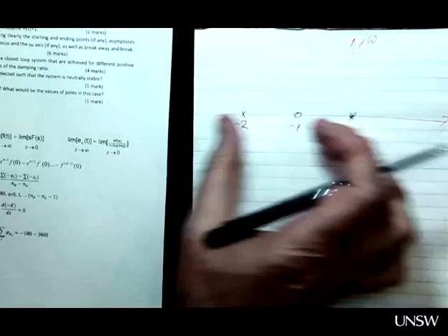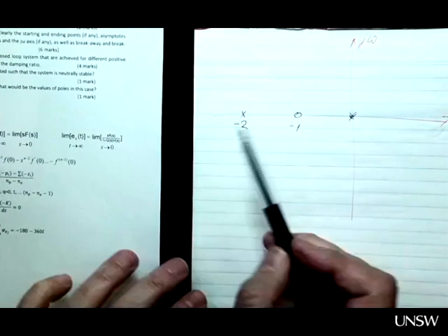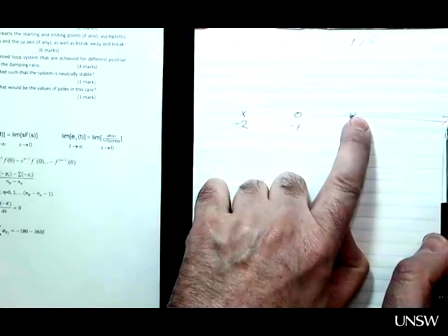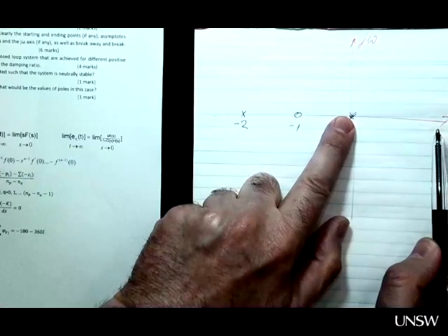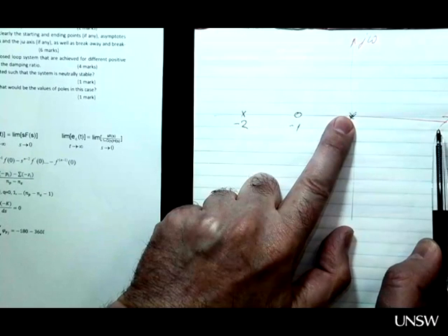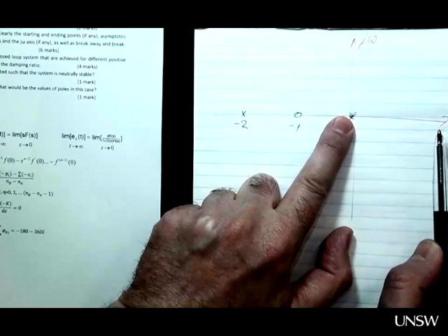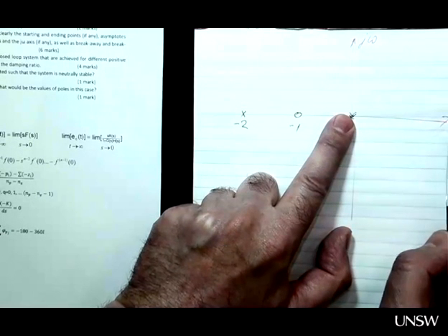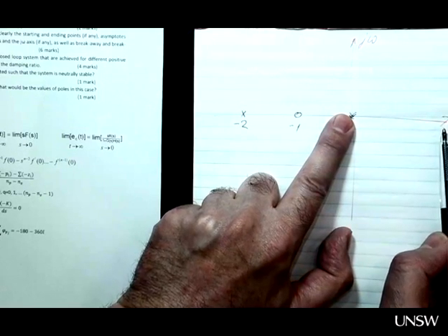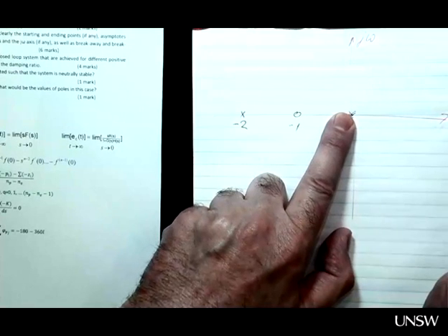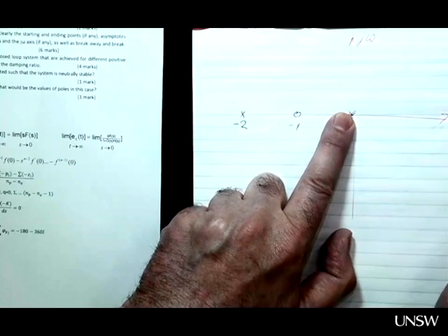So the next important rule is to identify the segments of the real axis where the root locus exists. First of all, how many segments do we have? 1, 2, 3, 4. A segment either completely belongs to the root locus or completely does not. There is no partial belonging. Does this segment completely belong to the root locus or not? It doesn't. Why? Because the number of singularities to the right of this segment is an even number, which is 0. There are no poles and no zeros to the right of this huge segment, so there is no root locus on this part of the real axis.